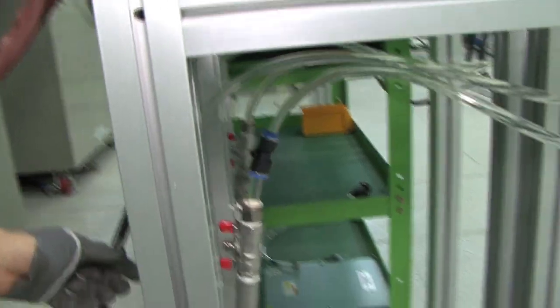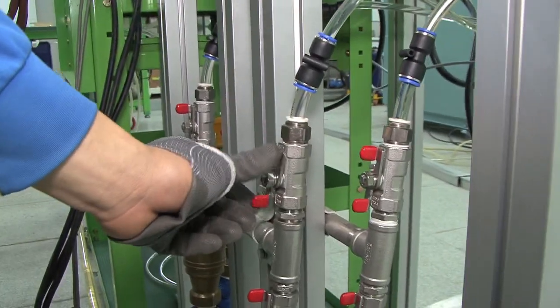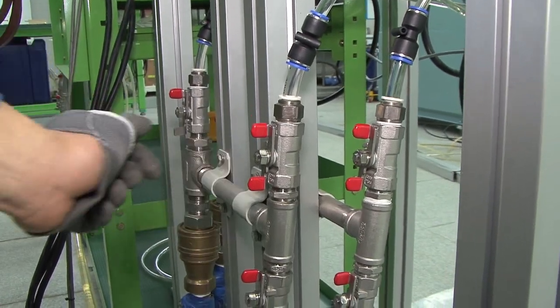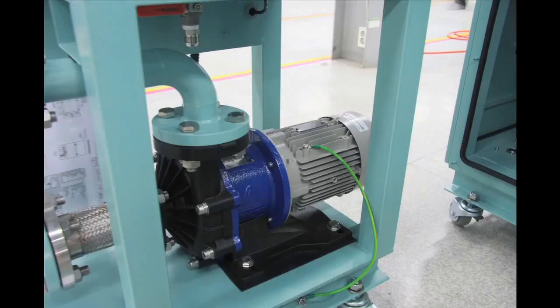Open the valve installed in the inlet and outlet of FTU. Refer to checkpoints before operation. Check leakage from FTU tank and ECU, PRU, cooling pipes. Supply cooling water, fresh water, if the cooling water is insufficient. In case of long-term storage, if the same problem persists, please contact the manufacturer.